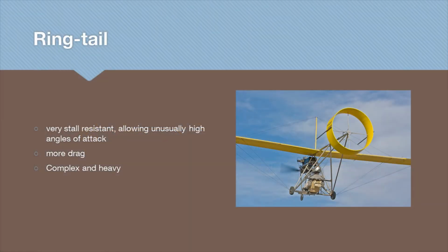The ringtail is very stall resistant, so it allows the aircraft to fly at a very high angle of attack. However, the ringtail usually needs to be quite large, so the drag will be higher. Also, this kind of configuration is more complex and heavier when compared to other designs.